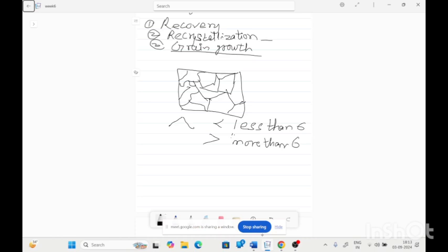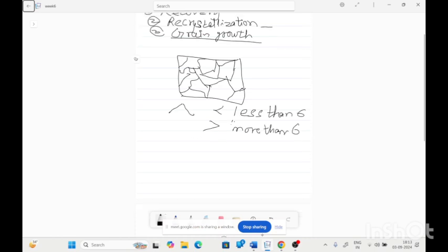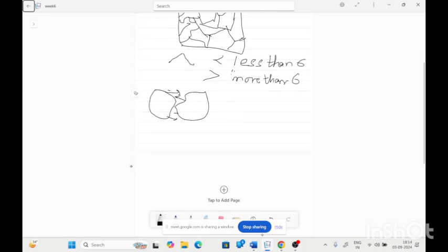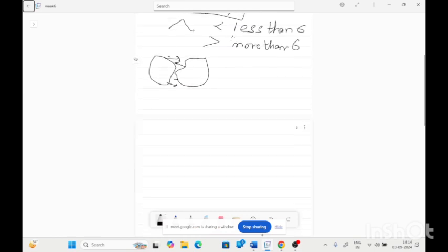So the grain growth happens due to grain boundary migration. Means if there is one grain and another grain, it will start growing in this direction or in this direction. This depends on the curvature of the grain boundary also. So grain boundary migration occurs so that it can consume the rest of the strained grains.